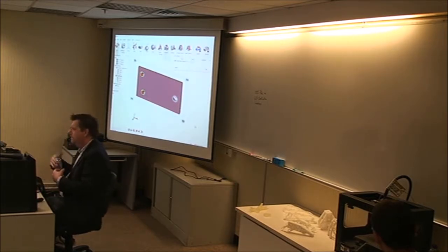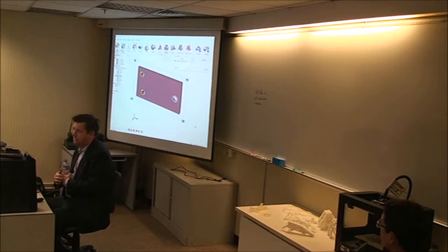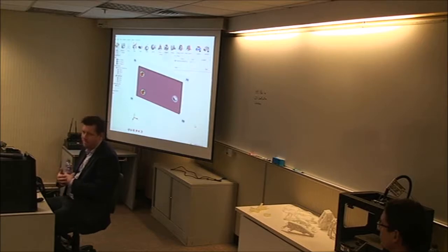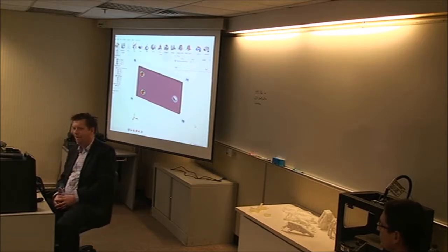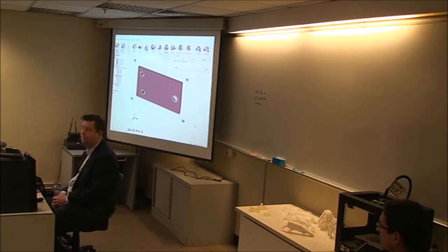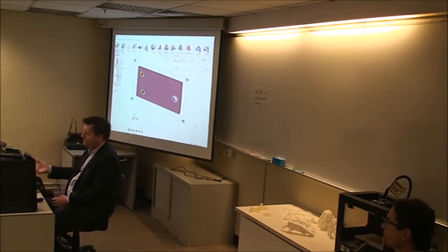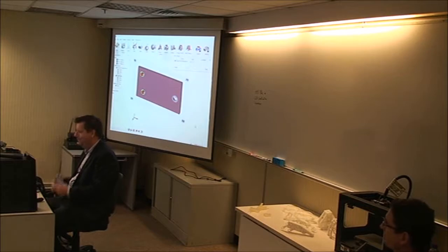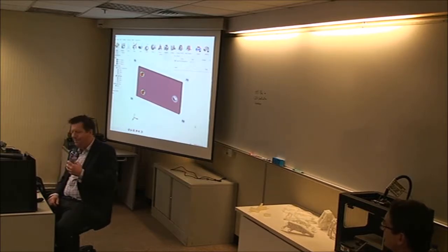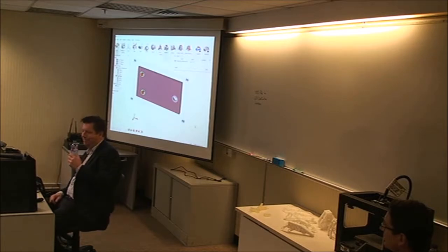So again, in the background, it's using SimLab to build the mesh. Once the mesh is built, it writes an OptiStruct file, which is our very advanced FEA solver and optimization tool. And we'll then launch that. When it's finished, we can get the results into Inspire format and read them back in. So what would have taken lots of manual work not so many years ago is now pretty automated.